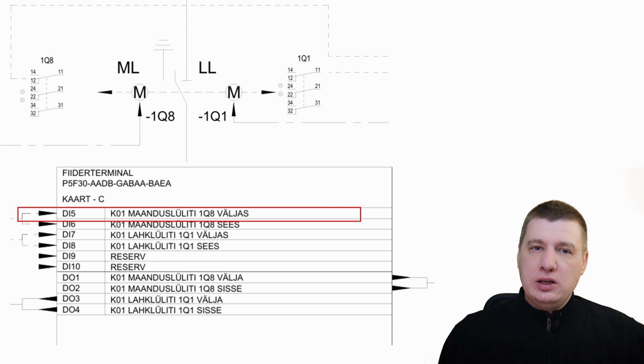Digital, this is reflected on your mimic display. The F switch symbol on the single line diagram will be shown as an open contact, providing a real-time snapshot of the bay state. This isn't just for show, the signal is a vital part of the object block matrix. The P5 is programmed with the safety interlocking.